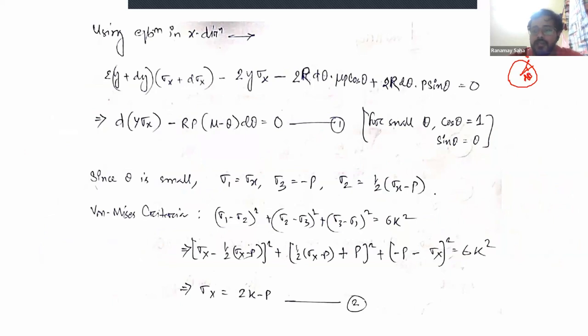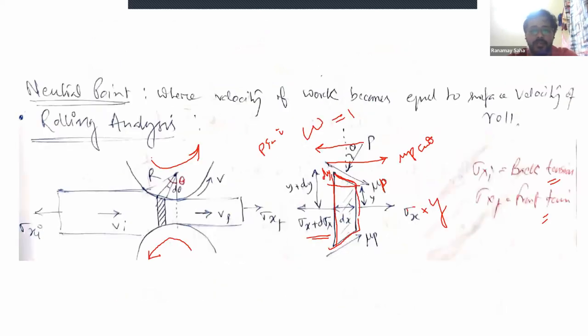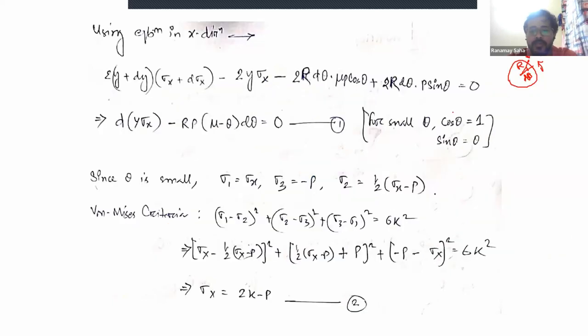So what is the arc length, right? This is R, and the arc length becomes R times d theta. For both sides you have a 2 multiplied, and then this is the frictional force, and this is again acting on your left-hand side, p sin theta. So that's why it is a positive sign. The whole force balance you equate to 0, and you come down to this particular expression after just resolving. I have excluded some intermediate steps which you can do at home.